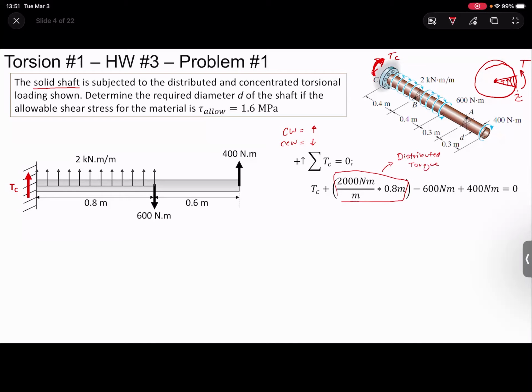So the thing to remember with this is, since these are torques, we don't multiply them by a distance. External moments or external twists on our shaft are not like a force times a distance that you would see when doing summation of moments. Think about these torques as all applied across this axis that I just showed.